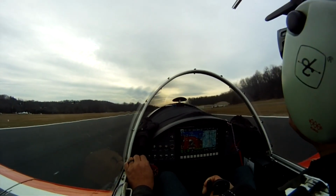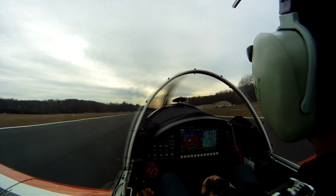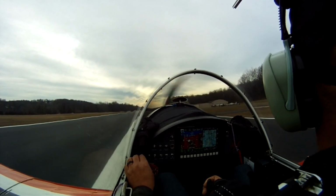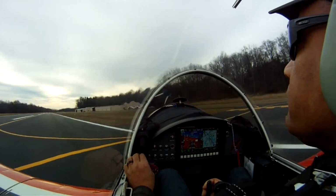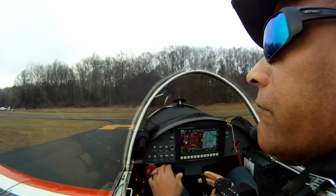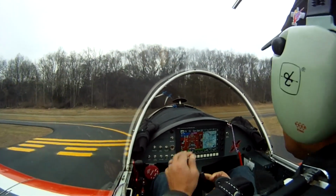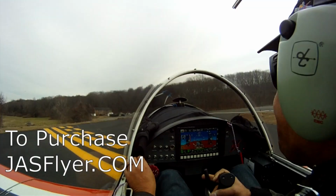If you're set up for audio recording, take advantage of that by recording the automated weather transmissions to save the wind data, and reciting aloud the flap setting and any other important configuration data. If at all possible, repeat each combination of landing factors at least 3 times to minimize errors introduced by your EFIS.